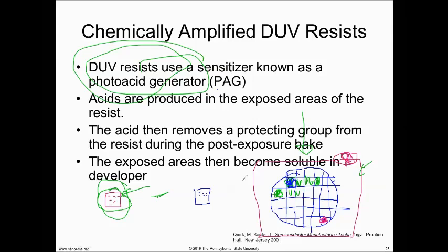I can increase my light energy, and we do that. Answer number one. The other answer is, and what we do with deep UV resist is, we do like a sleight of hand. We trade energies. So instead of just doing light energy, we do light energy and it sets up the response. We do work with light, and then we finish it with heat later on.